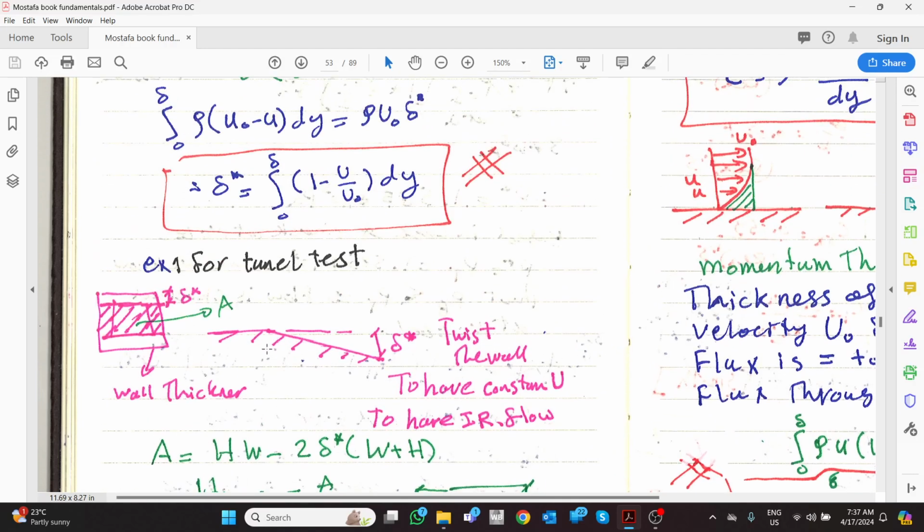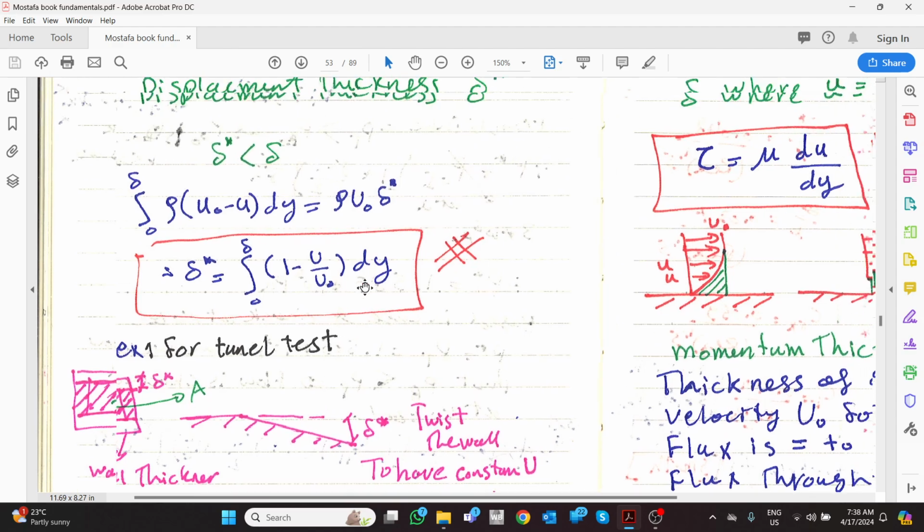Okay, but this is for you if you're doing a simulation, for example for a wind tunnel, or you're doing CFD in a wind tunnel, and you need to define what the environment limits are. If you don't care about the viscous force, the viscosity or the shear on the floor, whatever, but you care about the flow itself, you need to take this into account to simulate correctly.